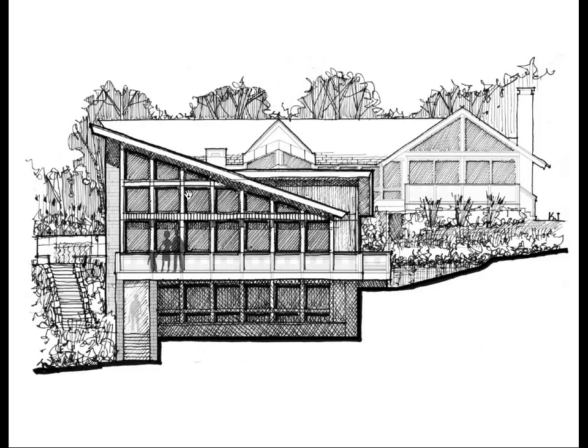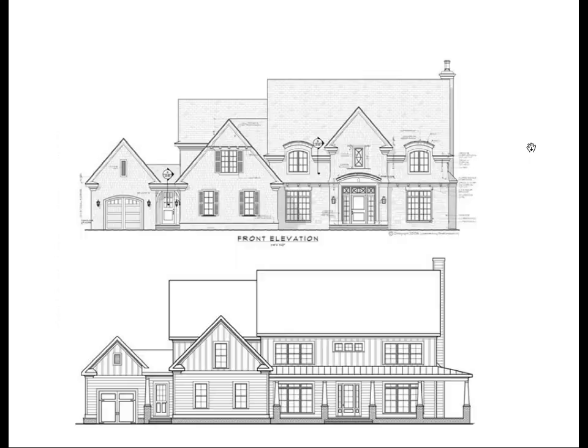Does everyone kind of see how that's starting to work? As you start to draw your elevations, you need to keep that in mind. I'll talk about some new layers that you can create today, so that when you start drawing those elevations, that starts to make sense. I won't talk about all of these for too long, but you can see the very similar elements. This part of the house is the closest to us, so it has a little bit thicker lines than the areas in the back.